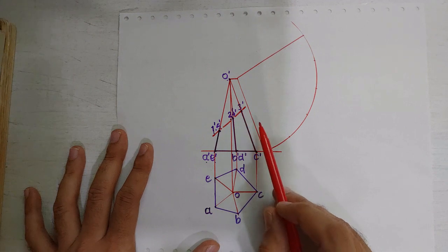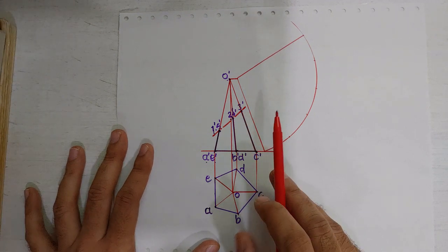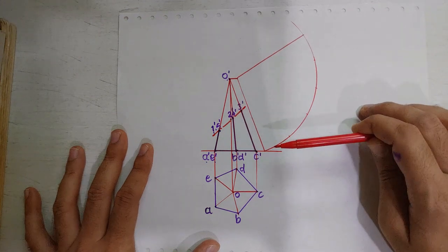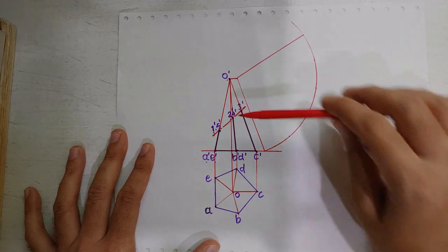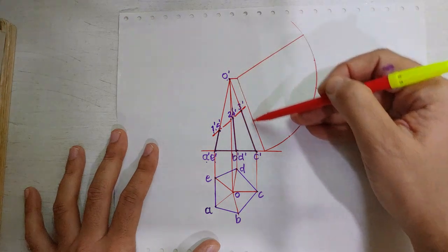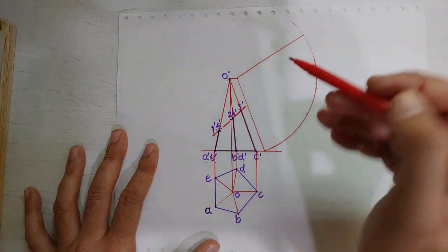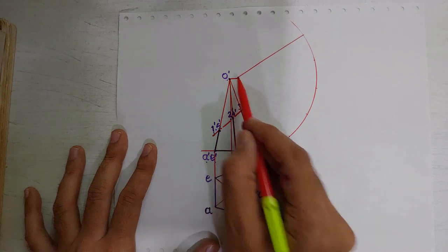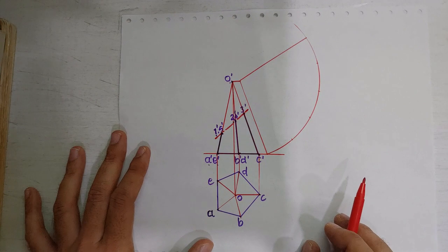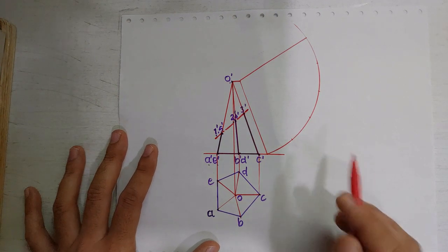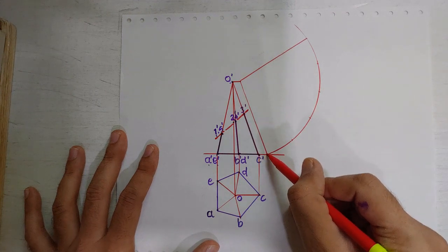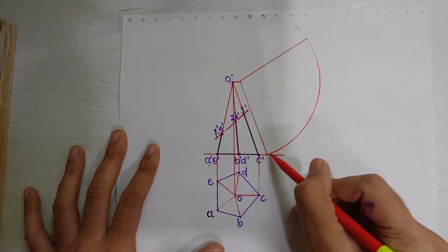Always remember that when we develop the surface, we have to draw the first line with true length of the edge. So here this is O prime C prime, so we will draw a line, this line, which is parallel to O prime C prime with the same length. So I have taken projection from O prime and C prime and the line. Then we have to take this point as center and this length as a radius, and then we have to draw an arc,